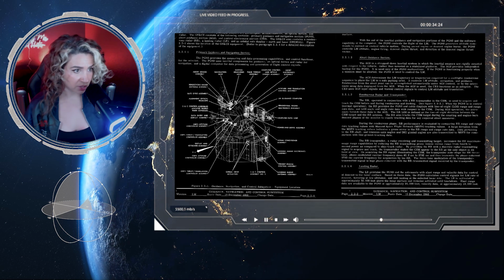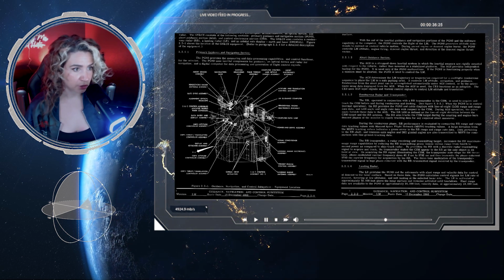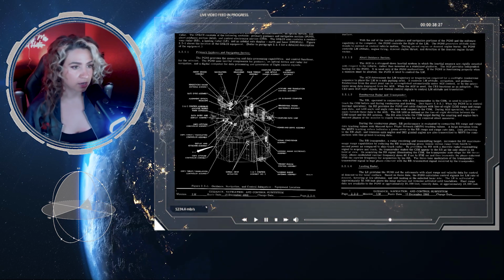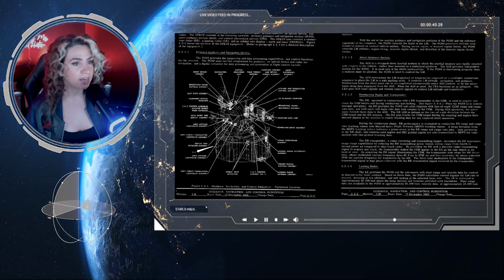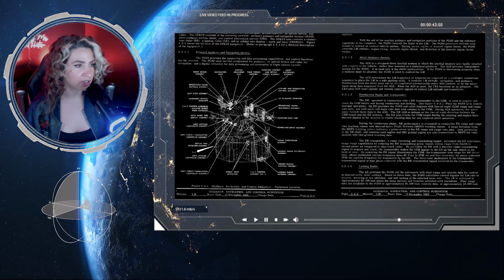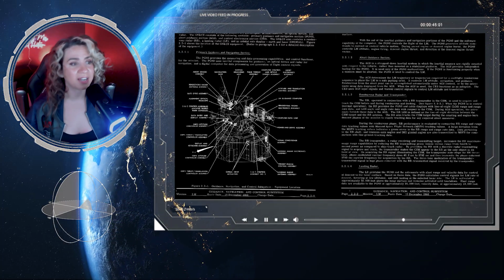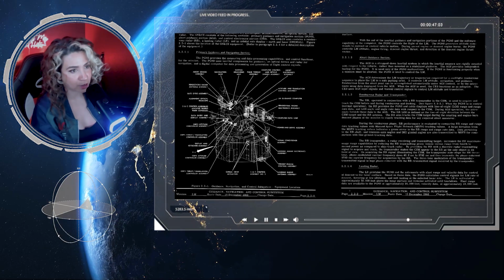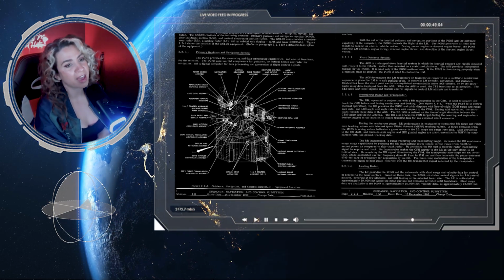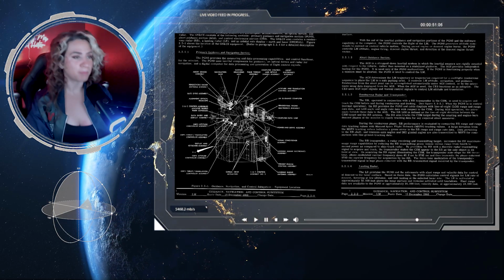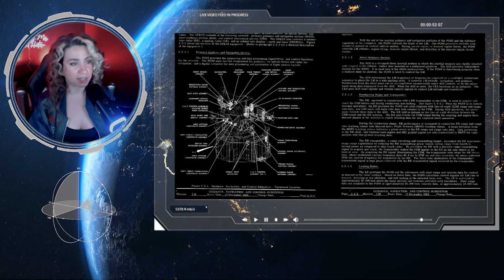indicate a gross error in the RR range and range rate data. Data pertaining to the RR shaft and trunnion axis angles and IMU gimbal angles are also transmitted to the MSFN for comparison with the ground tracking data.